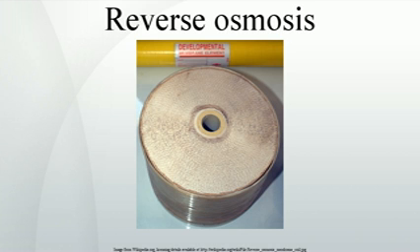In the production of bottled mineral water, the water passes through a reverse osmosis water processor to remove pollutants and microorganisms. In European countries, though, such processing of natural mineral water, as defined by a European directive, is not allowed under European law. In practice, a fraction of the living bacteria can and do pass through reverse osmosis membranes through minor imperfections, or bypass the membrane entirely through tiny leaks in surrounding seals. Thus, complete reverse osmosis systems may include additional water treatment stages that use ultraviolet light or ozone to prevent microbiological